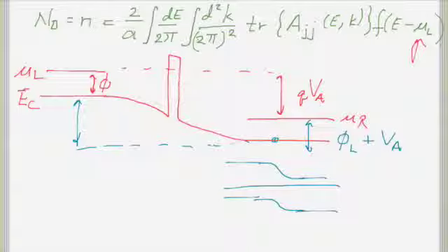So it can be kind of tricky choosing your potentials. But the real problem, you can do that, that's fine. But the real problem is that when you fix your potentials, this potential here and here is never going to move. That's fixed for all time. And then you send this off to your Poisson's equation, and you start self-consistently doing everything in between. And what invariably happens is you get a potential profile that looks like this. So the first node, there's a discontinuity.